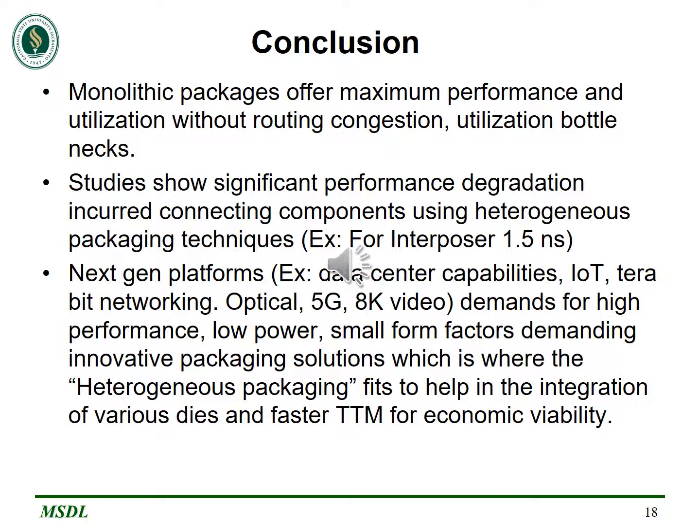Let's conclude this topic. Monolithic packages offer maximum performance and utilization without routing congestion and utilization bottlenecks. Studies show significant performance degradation is incurred connecting components using heterogeneous packaging techniques. For example, if we consider the interposer, it's 1.5 nanoseconds.